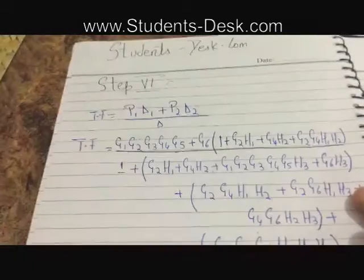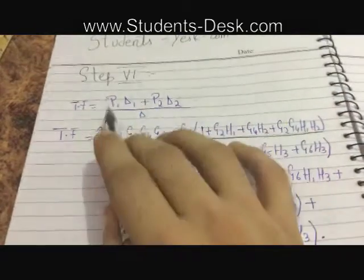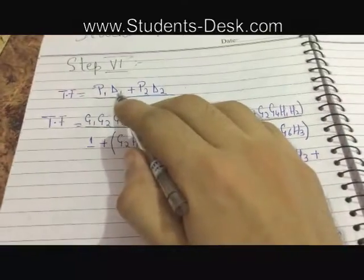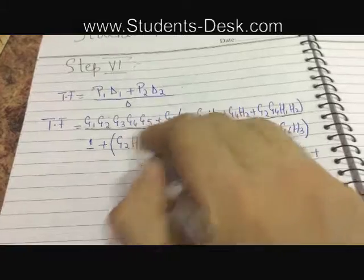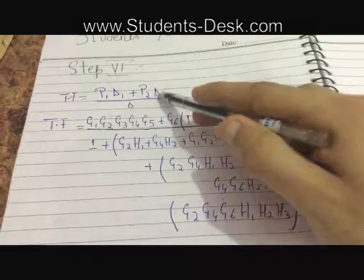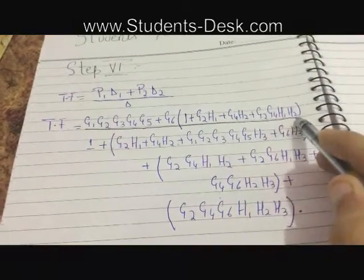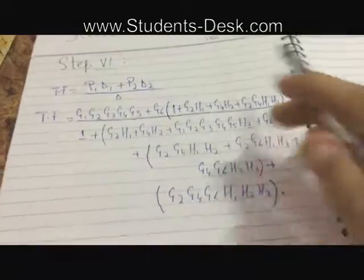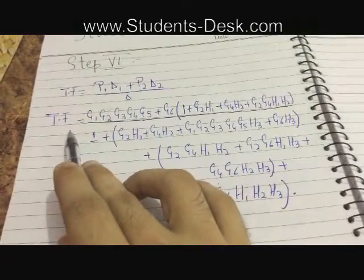So step 7 will be applying Mason's gain formula. We have 2 paths, P1 and P2, and delta 1 and delta 2, divided by delta. Delta 1 is 1, so 1 multiplied by path 1, which is G1, G2, G3, G4, G5, and path 2 is G6, and delta 2 is 1 plus G2 H1 plus G4 H2 plus G2 G4 H1 H2, divided by the value of delta, which we found in step 5. So simply place the values and you will get the transfer function of the signal flow graph.